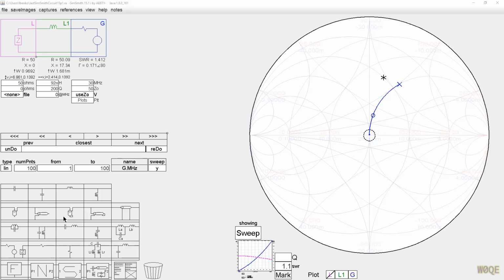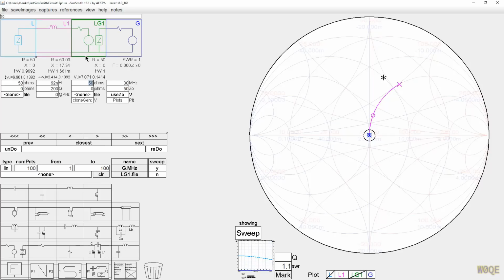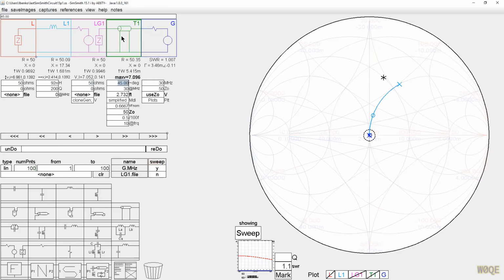I've made comments in the past about wiring also looking like a transmission line, and it does. It actually looks more like a transmission line than a raw inductance because the return current, when you build a circuit, will try to come back on the path of least impedance, and that path always tries to be close to the conductor where the outgoing current is.